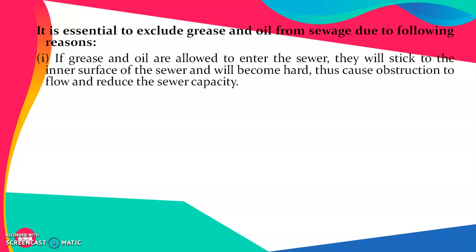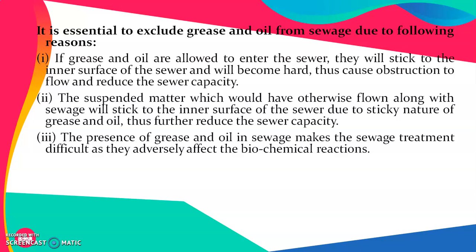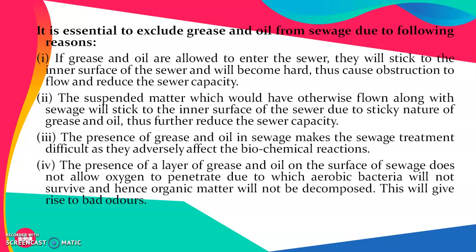Now, if grease and oil are allowed to enter a sewer, they will stick to the inner surface, become hard and thus cause obstruction. Suspended matter may also stick to such a sticky inner surface and reduce the sewer capacity. The presence of grease and oil in sewage makes sewage treatment difficult as they generally interfere with the biochemical reactions.